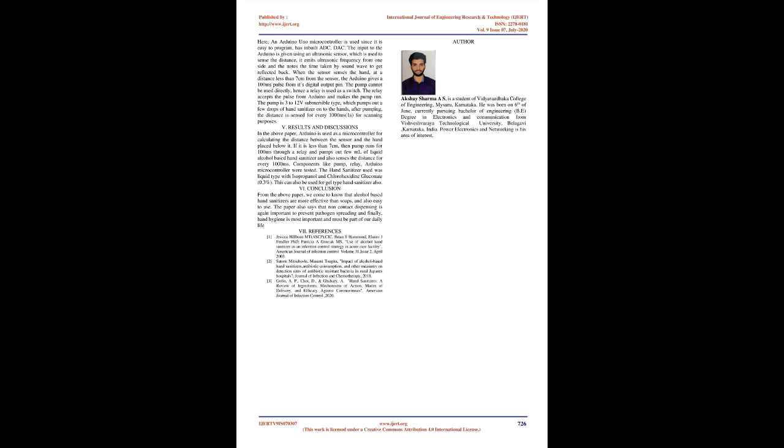Here, an Arduino Uno microcontroller is used since it is easy to program and has inbuilt ADC, DAC. The input to the Arduino is given using an ultrasonic sensor, which is used to sense the distance. It emits ultrasonic frequency from one side and then notes the time taken by the sound wave to get reflected back. When the sensor senses the hand at a distance less than 7 centimeters from the sensor, the Arduino gives a 100 millisecond pulse from its digital output pin.